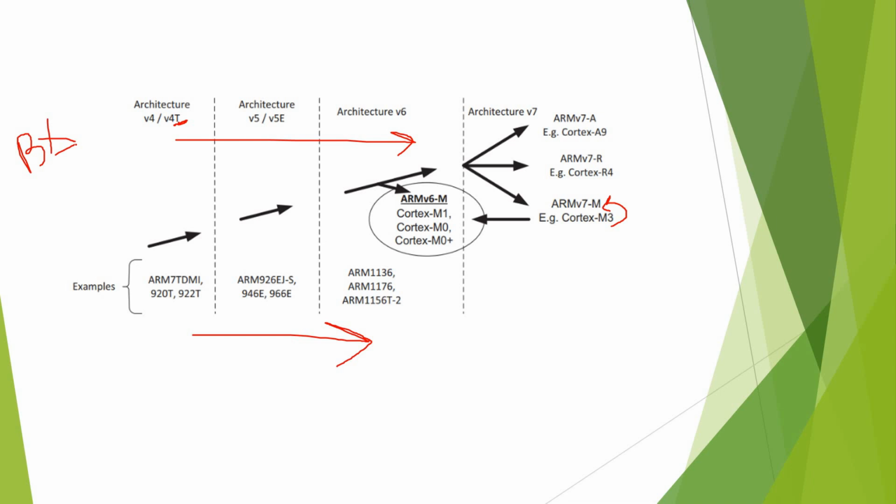One important piece of information: 32-bit instruction encoding actually refers to ARM state. So if the processor is executing a 32-bit instruction, then it will be in ARM state. And if it is executing a 16-bit instruction, then it will be in Thumb 1 state, or Thumb state.